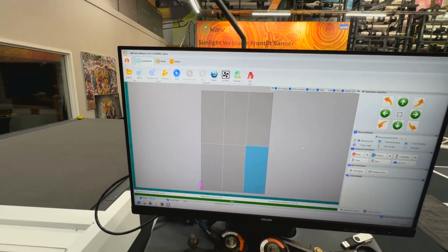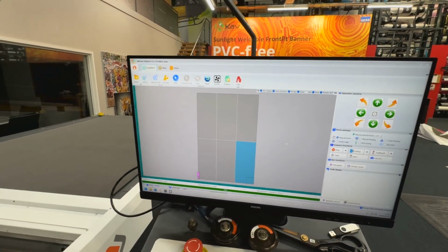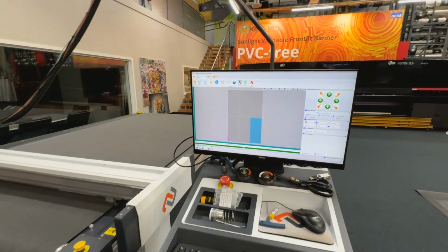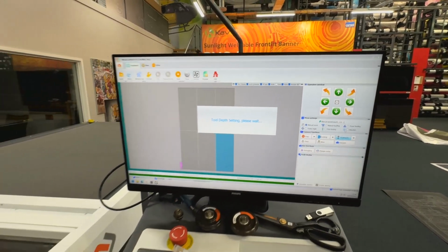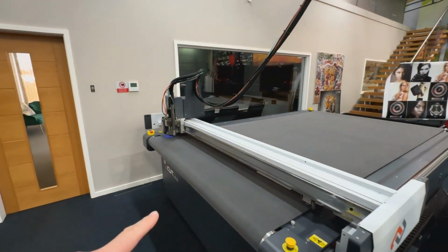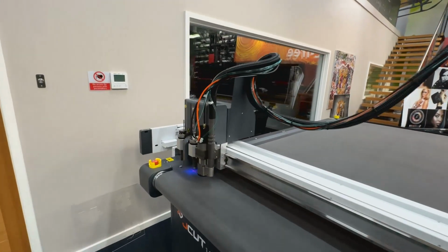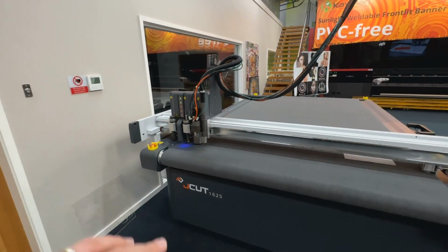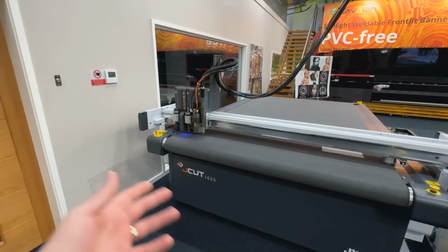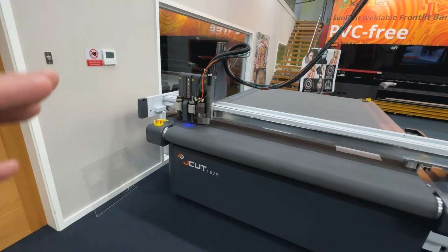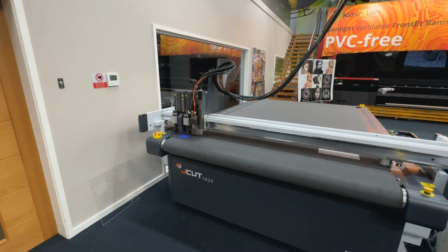So that's now saved our tool height, our tool depth. So if I was to do my tool depth again now here, that's going to use that new value for our tool height. So that's our global height done. So now in OptiScout, we can add our 0, 1, 0, 2, 3, 4, and 5 again, but we're now adding it from a new starting position.